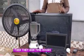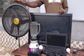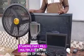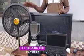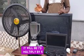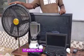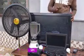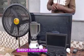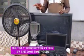Then the runtime hours, for example, the standing fan is 72 watts. So if I want to know the daily energy consumption of this standing fan, I will multiply it by the number of hours I will be using this fan daily. So let's assume I'm using it for 5 hours. It will be 72 multiplied by 5. So whatever I have is the total daily energy consumption of this standing fan. So always do well to carry out a load audit to know your energy consumption. So to know the energy consumption, multiply your power rating by the runtime hours.